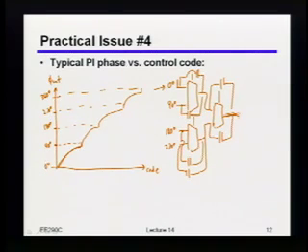Because in one case, it's pulling you forward, and in the other case, it's pulling you backwards. So now, depending upon which thing I've actually chosen, I'm effectively going to be creating a different unintentional phase interpolation at the output, right? Because as an example, imagine that I had, let's say, 90 degrees here and 180 degrees, and let's say I flipped it so that now instead this becomes 0 degrees and this becomes 270 degrees. If you look out over here, phase interpolating between those two is not at all the same, right? Does that make sense to people?